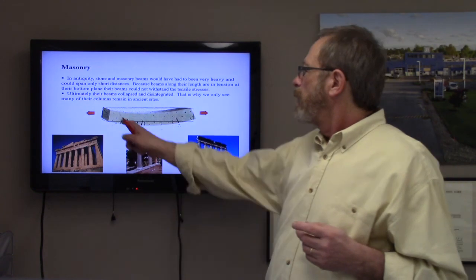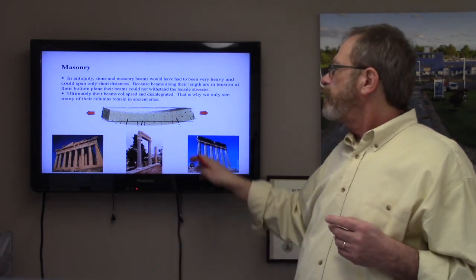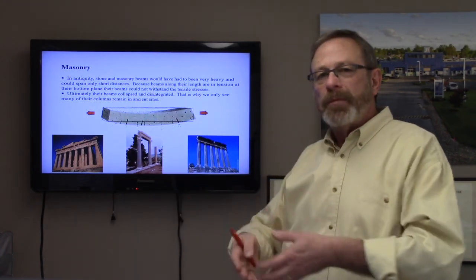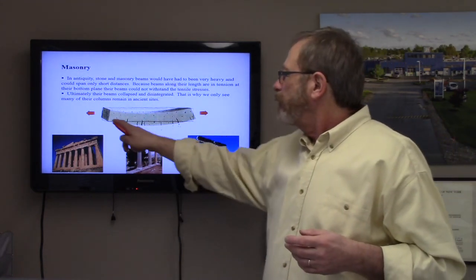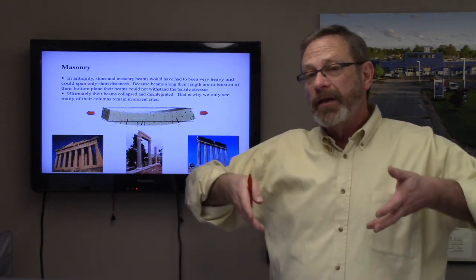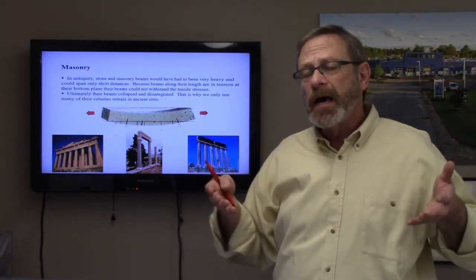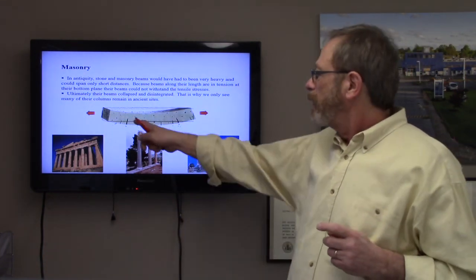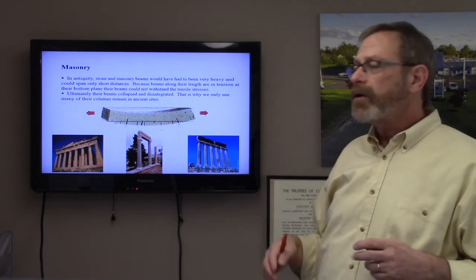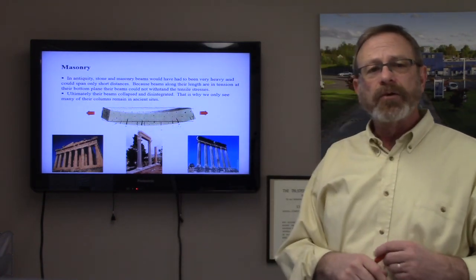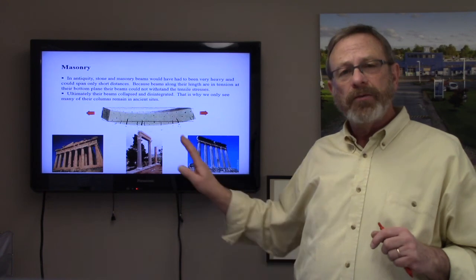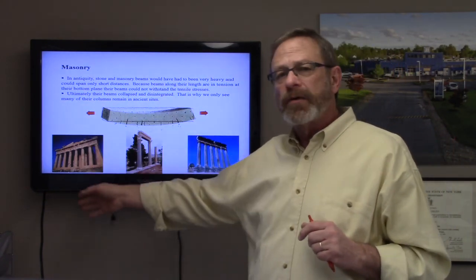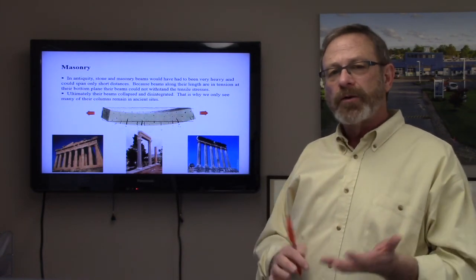So we saw earlier beams that were restrained on both ends. The tops we said were in compression and being pushed together. The bottoms were being pulled apart. And when you have a material that's not good in tension, it's not going to be good as the bottom part of your beam. So granular materials, bad in tension, are going to start to fail, crack, and ultimately collapse and disintegrate on the ground. So masonry used in antiquities, we have a lot of surviving examples of columns, because columns are granular, stone, brick, or masonry.